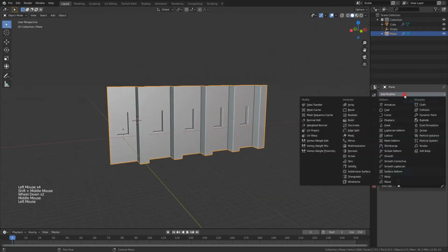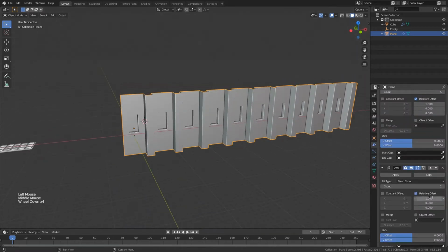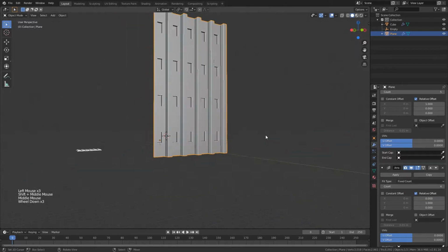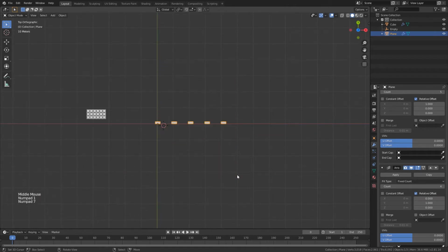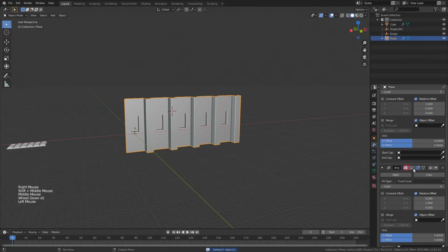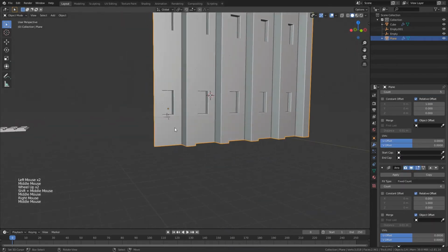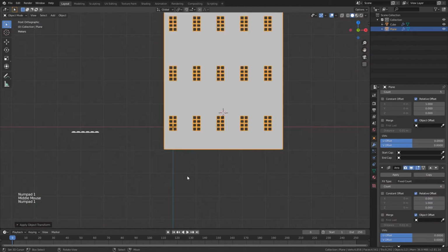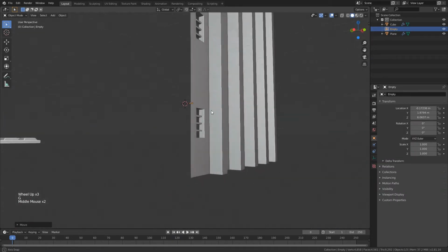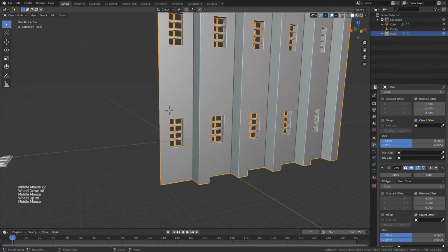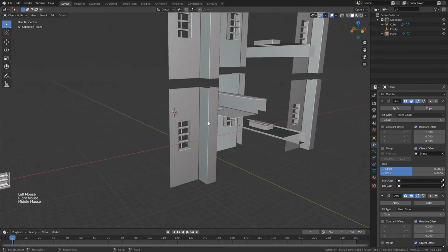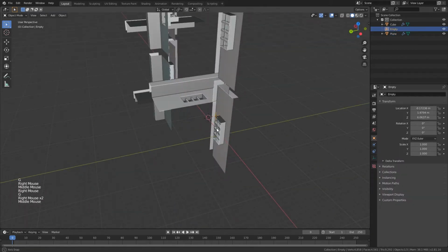Now imagine if I add one more array modifier, and instead of what I did before, I use vertical duplicates. And if I go to the top view and bring one empty object over here, let's see if I can modify this further. I'll create one empty object over here, plane axis. Now in the first array modifier, I'll select this one as a driver for transformation.